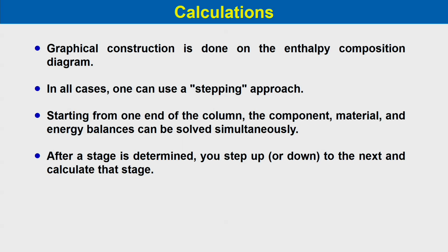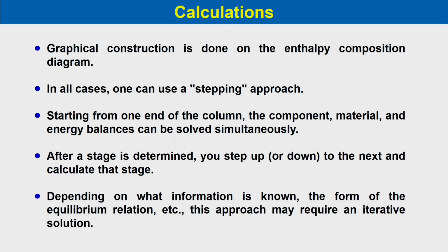After a stage is determined, you can step up or step down to the next and calculate that stage. Depending on what information is known, the form of the equilibrium relations and other things, this approach may require iterative solutions. Regarding the determination of the number of trays using the Ponchon-Savarit method, we will consider it in the later part of our discussion.